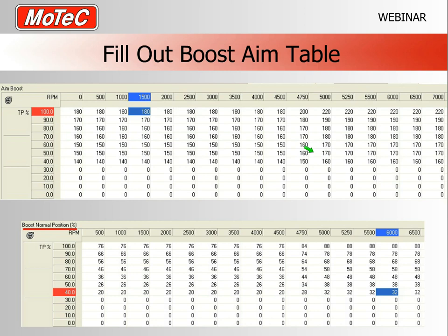The drive-by-wire motor had another compensation issue, and the drive-by-wire motor was locked at 30%, and it was still making nearly full boost at that. So a way of giving that feel back to the throttle is to make the boost proportional to the throttle. So when the customer starts pulling the throttle off, the boost starts coming back. Does that answer your question, Nils?